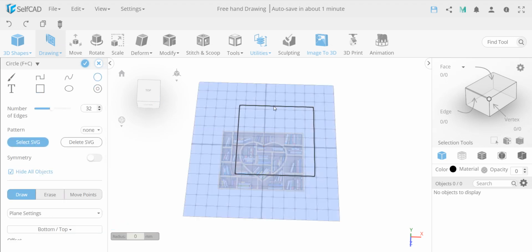So if I'm going to draw a circle over here, this will by default cut in over here. You see, it saves all of this time from trimming. But if I want this to be a hole in, like the other type, I can simply click on eraser and you start erasing. So in most cases, you control that yourself. You click erase and you start drawing things like this. And same thing, I can draw an eraser over here and it creates a hole over here. So the red is always where it creates a hole. This is not a hole because it's open. You see, the red is where it creates a hole. If I finalize this, it will create a hole.